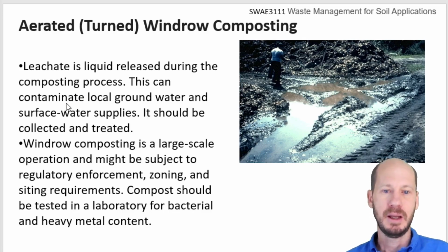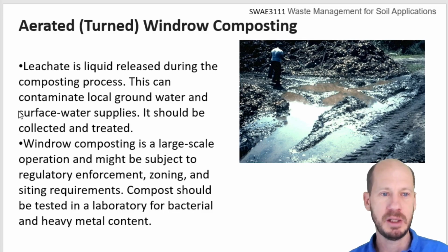So it's highly recommended that if you have large windrow composting operations, you have a cemented patio where you can collect the leachates and remanage them, even use them back for the irrigation of the compost piles later on, or treat them. This is highly recommended to avoid the leachates reaching aquifers and contaminating water courses.